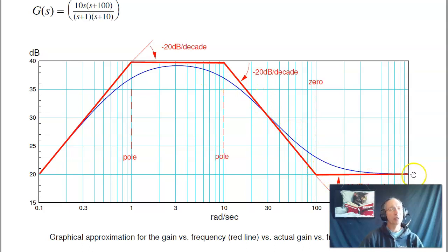So the way we used to draw the Bode plots is you draw the straight line approximations. Mark at the corner, I'm down 3 dB, so go from one asymptote, pass through this point, hit the second asymptote, pass through this point, go to the third asymptote, pass through this point, go to the fourth asymptote. And that's how we would draw the Bode plots.